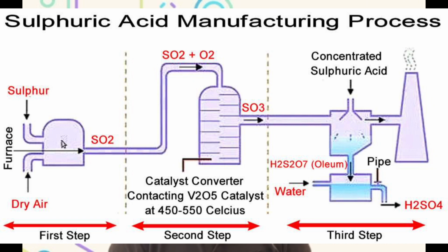However, not all the raw materials were completely converted from sulfur dioxide to sulfur trioxide. Some of the sulfur dioxide and oxygen remained in the gases at the base of the absorption tower. These gases are run through the fourth bed of the converter once again, after which approximately 99.5% of the sulfur dioxide has been converted into SO3, according to Fiberglass Products Company.